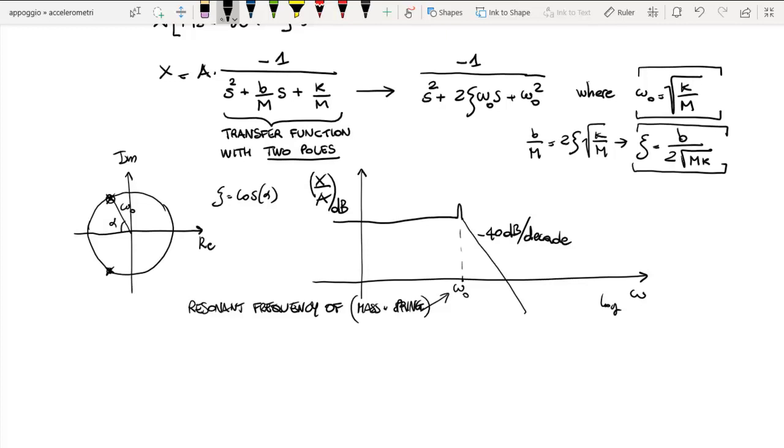So if we measure the average position of the mass, it gives you something which is proportional to the acceleration of the case. What we measure is the acceleration of the case, and then we assume that the case is attached to the object, and therefore it has the same acceleration as the object.